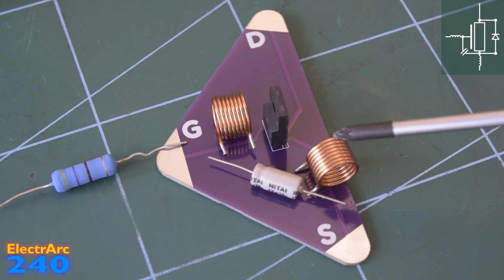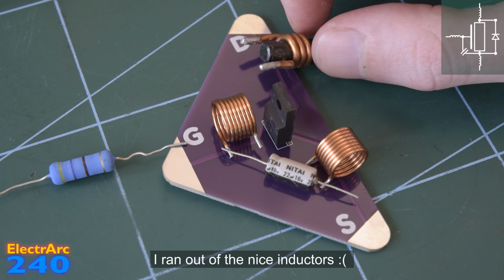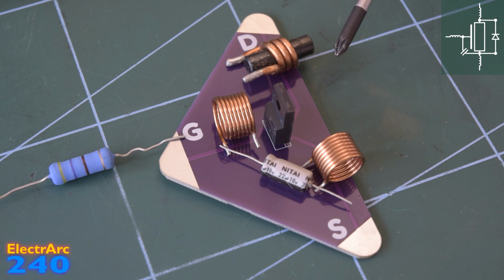The second impact of the source inductance is on the drain-source voltage. This is also affected by the drain inductance, so I'm going to add that in now too. Together, the source and drain inductance can once again result in ringing and overshoots, this time between the drain and the source rather than the gate and the source. These overshoots are typically much bigger than those on the gate because the currents involved are much higher. In many applications, this inductance is more dependent on circuit layout and PCB design than the actual MOSFET itself, as these things can add sometimes significant further inductance.